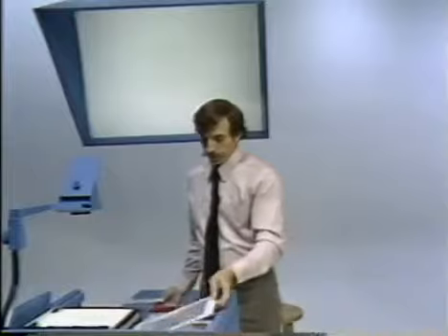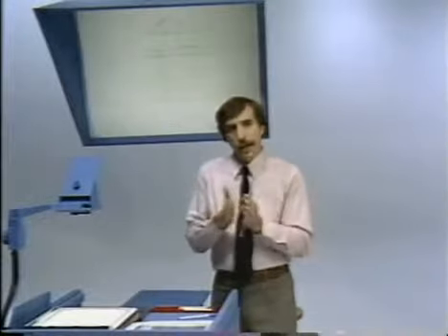Well, that's what happens in discrete time, and pretty much the same strategy works in continuous time. In particular, we can begin in continuous time with the notion of decomposing a continuous time signal into a succession of arbitrarily narrow rectangles. And as the width of the rectangles goes to 0, the approximation gets better. And essentially what's going to happen is that each of those individual rectangles, as they get narrower and narrower, correspond more and more to an impulse.